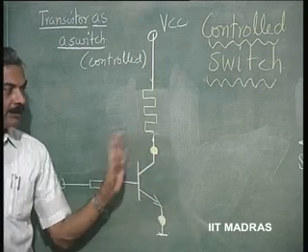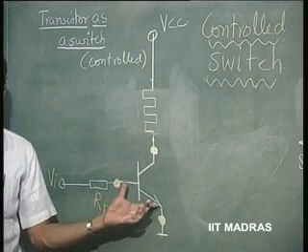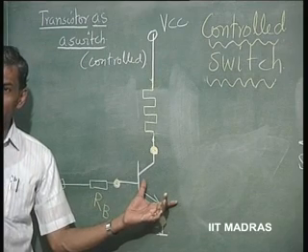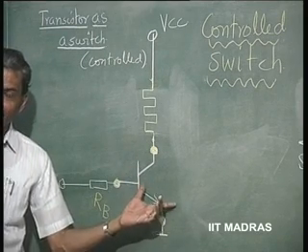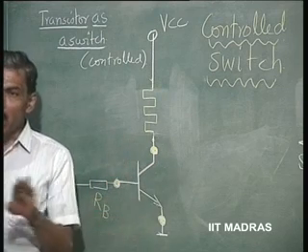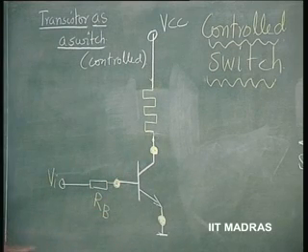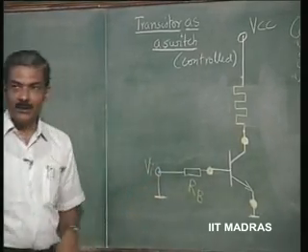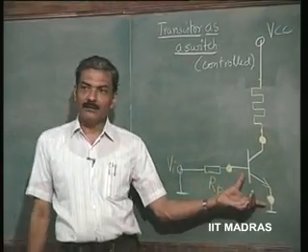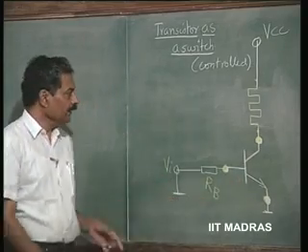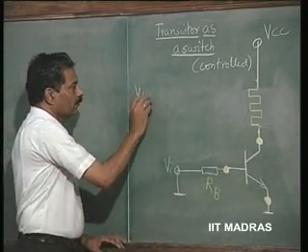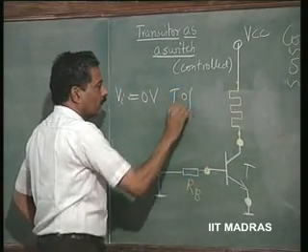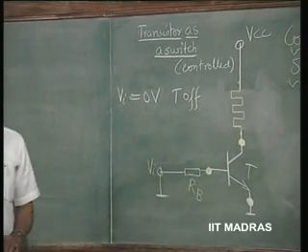We do not want this switch, which is now the transistor acting as a switch, to remain in the active region. So, this is the difference between amplifier and a switch. This transistor should not remain in the active region, either it should be off. Switching it off is easy. I can simply make this 0. So, this is not forward biased. So, if Vi is 0, transistor T is off. This is the simplest way to switch it off.